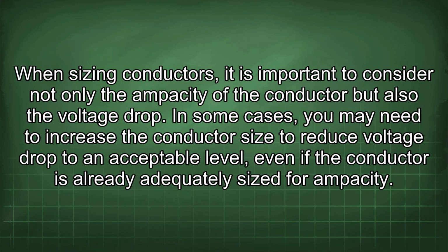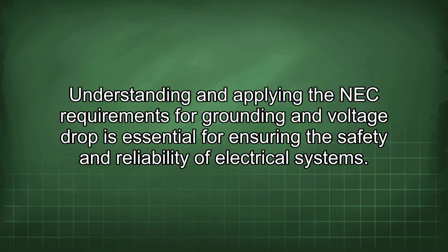When sizing conductors, it is important to consider not only the ampacity of the conductor but also the voltage drop. In some cases, you may need to increase the conductor size to reduce voltage drop to an acceptable level, even if the conductor is already adequately sized for ampacity. Understanding and applying the NEC requirements for grounding and voltage drop is essential for ensuring the safety and reliability of electrical systems.